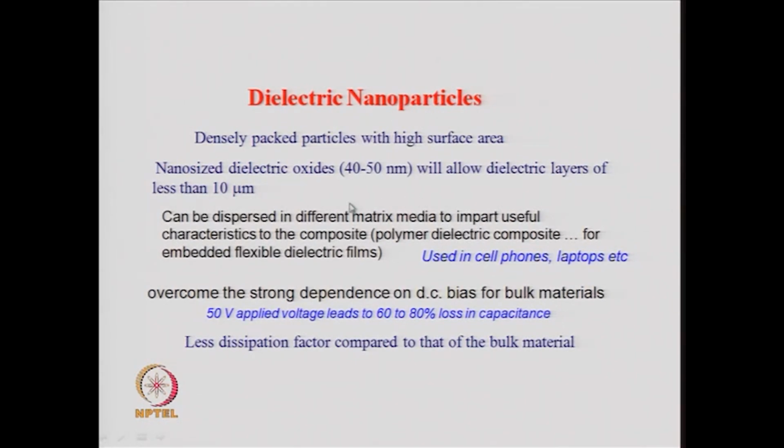The small size of nanoparticles will allow you to bring down the thickness of the layers of these MLCCs, the multi-layer capacitors, and hence these thin dielectric layers will allow you to make smaller devices. The other thing is you can make flexible films by making composites of these dielectric nanoparticles with plastics or with polymers.